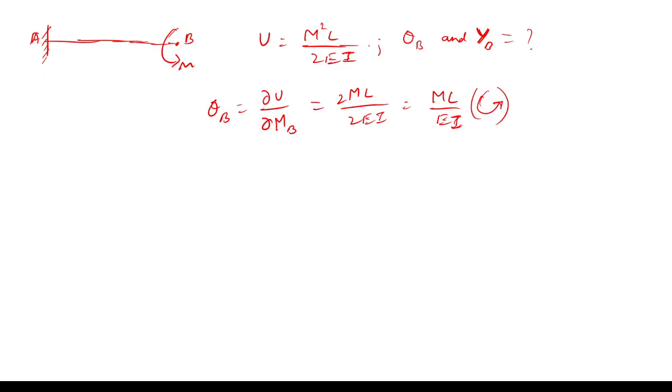So now, how can we find out the deflection? Here, as one person pointed out, we don't have any point load, so we can't directly have an equation of strain energy in terms of W and then partially differentiate that strain energy with respect to W to get the final answer. But here I am not having the strain energy in terms of W. So what I will do is introduce a dummy force, I mean dummy load.